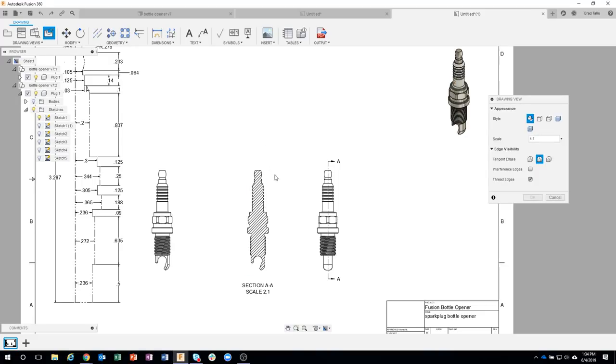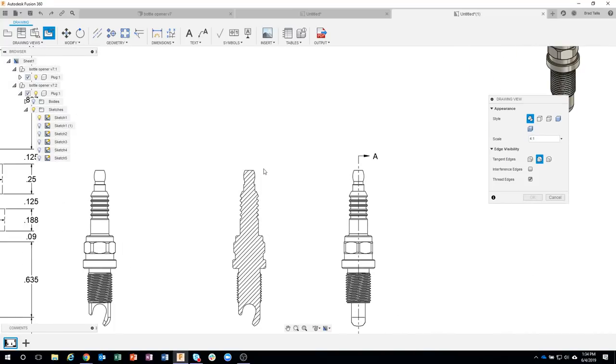What it's asking you, it's kind of hard to tell, is to draw a circle that encompasses the detail area, and it wants to know the center. So I'm going to start here, and you can see I clicked right about there, and then I start to move, and I'm now able to specify the size of my detail circle.